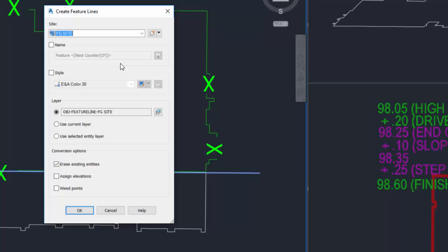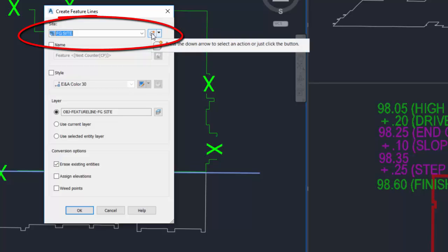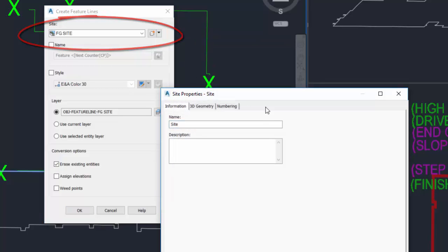The only time I really do the reset those settings in the commands is when I'm doing a lot of repeated work, and we'll start getting back into that here later on. But when we start to do the rest of the gutter for the parking areas and sidewalks and things like that, we'll repeatedly continue to use those same styles and that same naming convention and the same site, that sort of thing. But anyhow, enough of that. Let's go ahead and make the new site, and we can do that from here. So we're going to pick on the icon here, creates the new site.